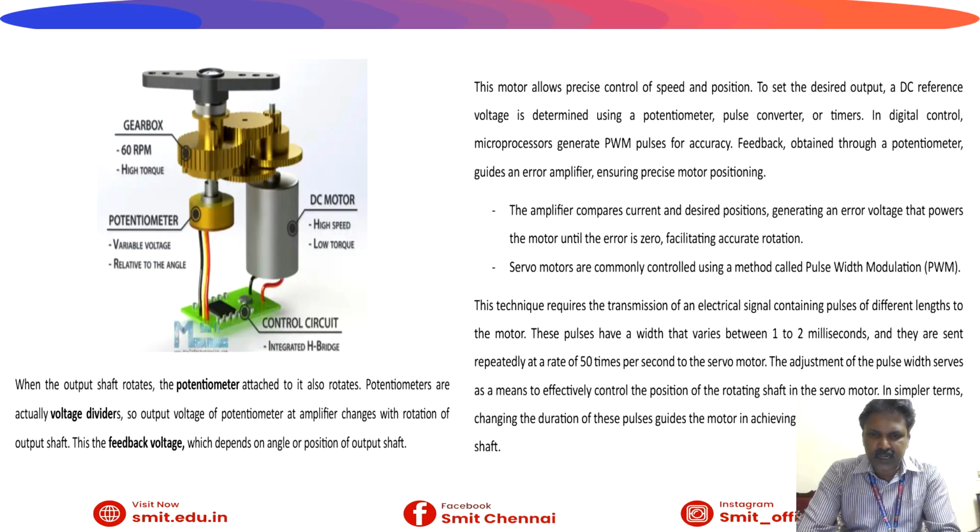In simpler terms, changing the duration of this pulse guides the motor in achieving the desired shaft position. That is the PWM, pulse width modulation. Based on the modulation of the pulse, we can change the duration, which guides the motor. We can change the position of the rotating shaft in a servo motor, and the position can also be maintained by adjusting the pulses.